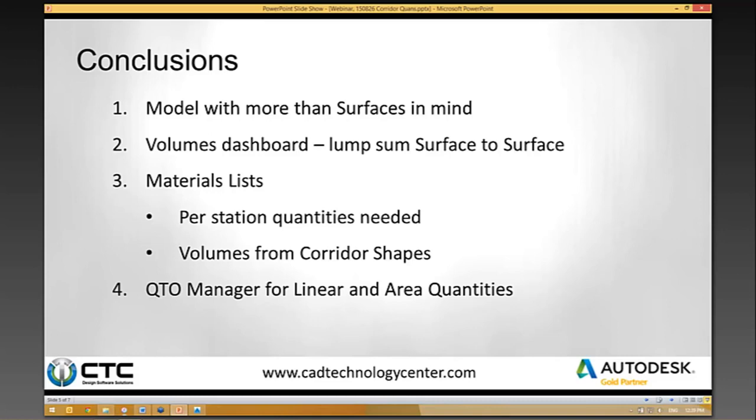The material list, this is per station quantities when you need that, or if you want to pull quantities from your corridor shapes. Unfortunately, you can't reference corridor shapes in QTO Manager. I wish you could, nevertheless, it's not there. And use QTO Manager for linear or area quantities.